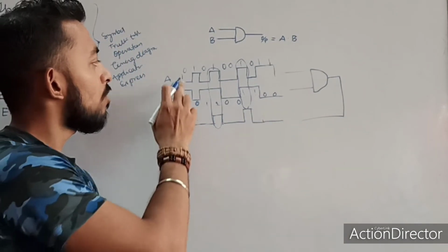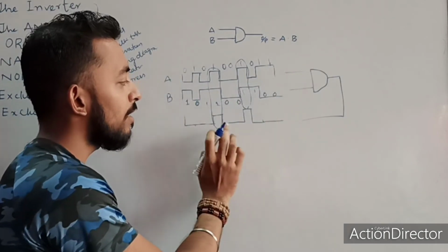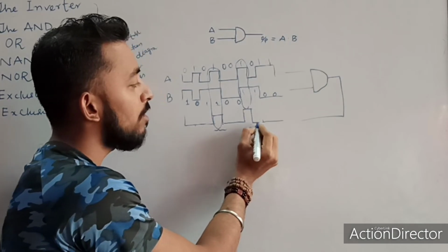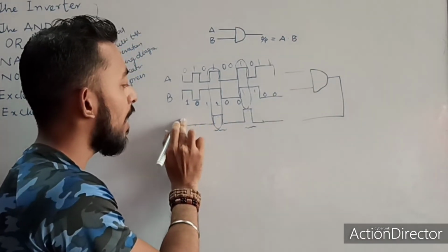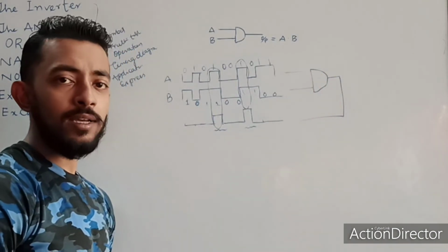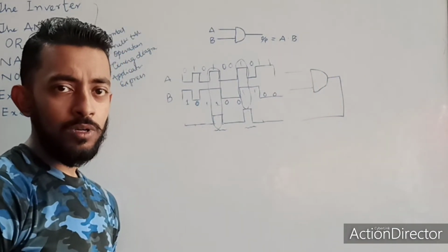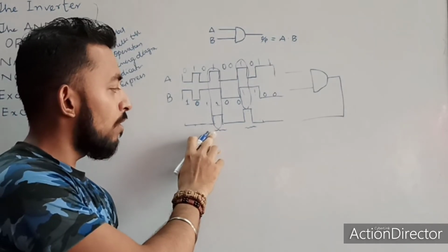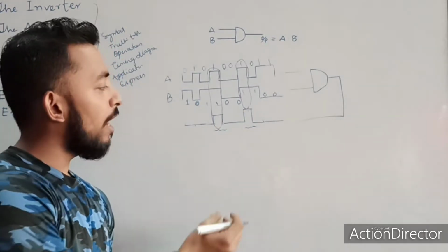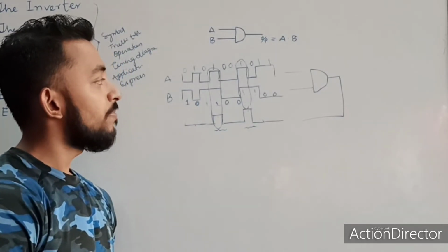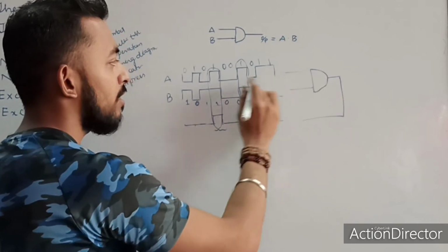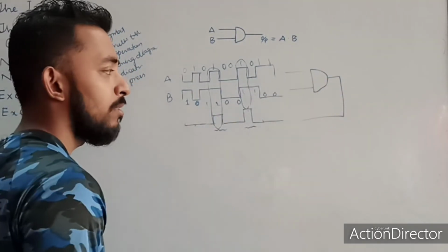So these are the two waveforms that are applied to the AND gate, and this is the output that I am getting. Here you can see for this interval and for this interval my output is high. Since there are no bubbles, no bubble means I will take the active high output. Active high means I will take the high values. And when there is a bubble, then I might take the low values. Similarly, you can add any 2 to 3 signals.